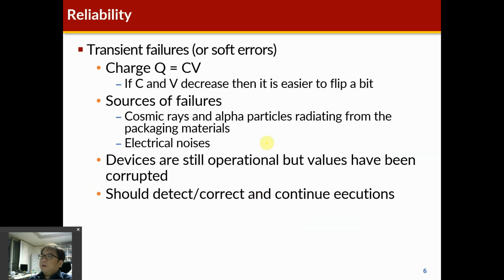And then reliability. Reliability is related to the correct operation of the CPU circuits. Every CMOS circuit device has capacitance, and when the switch is on in the PMOS part, the charge is filled in the capacitance of this CMOS circuit.